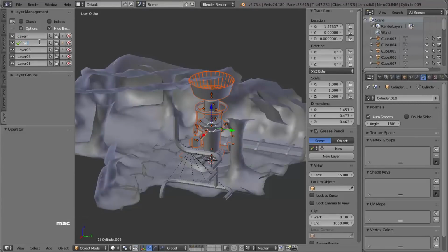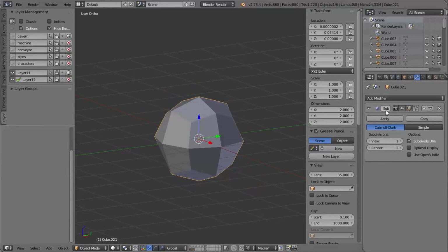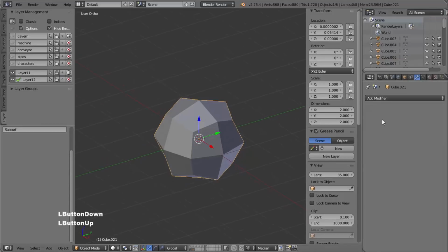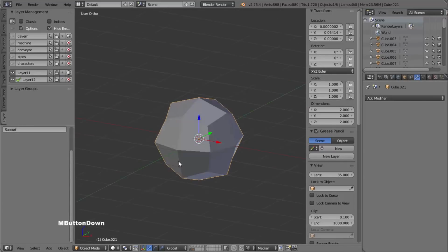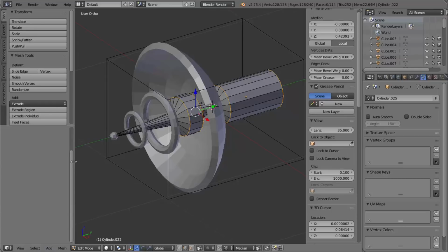We'll start with some organization, in particular the very handy layer management add-on. Then it's on with the modeling of the attachments. First up, it's the triple dish. There we'll make mention that you can automatically add a subdivision surface modifier onto an object with the Control and 1 shortcut, turning a cube into something much more sphere-like basically. We'll also look at selecting sharp angles automatically.